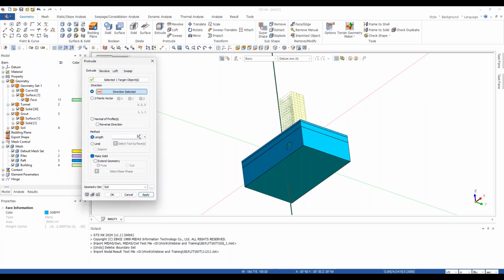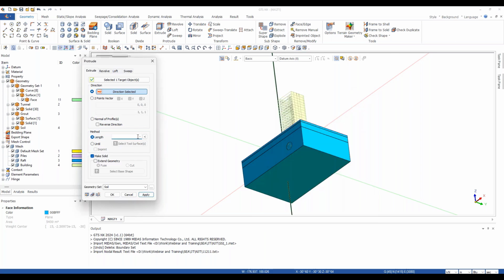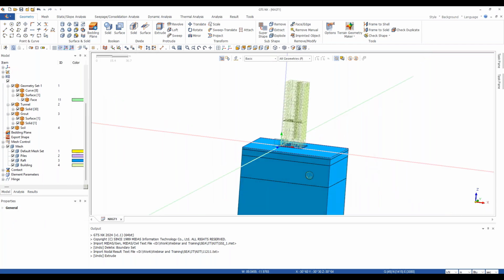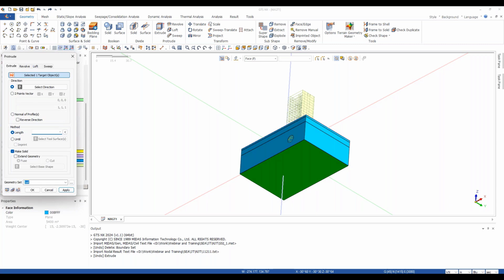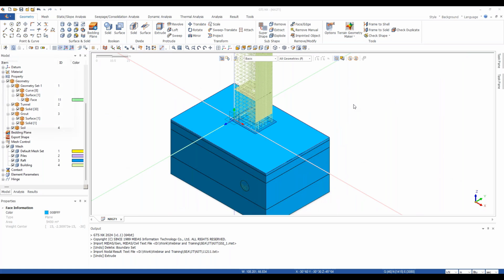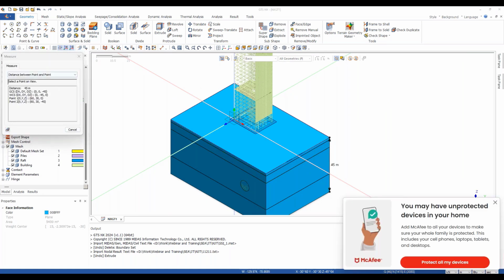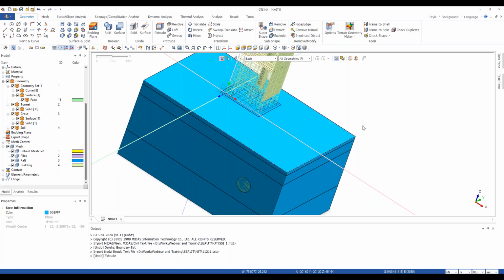Select the direction, and then let me select it for how much we have come so far: 2 meter, 6 meter, 22 meter. So we will have the last layer of 45 meter. Sorry, we just wanted to have 15 meter. So -15, so that in total, let me select the direction. As we have discussed, the length of the soil domain would be around 45 meter. If you see, we have the tunnel from this end extending till here. So now most of the geometry is created.